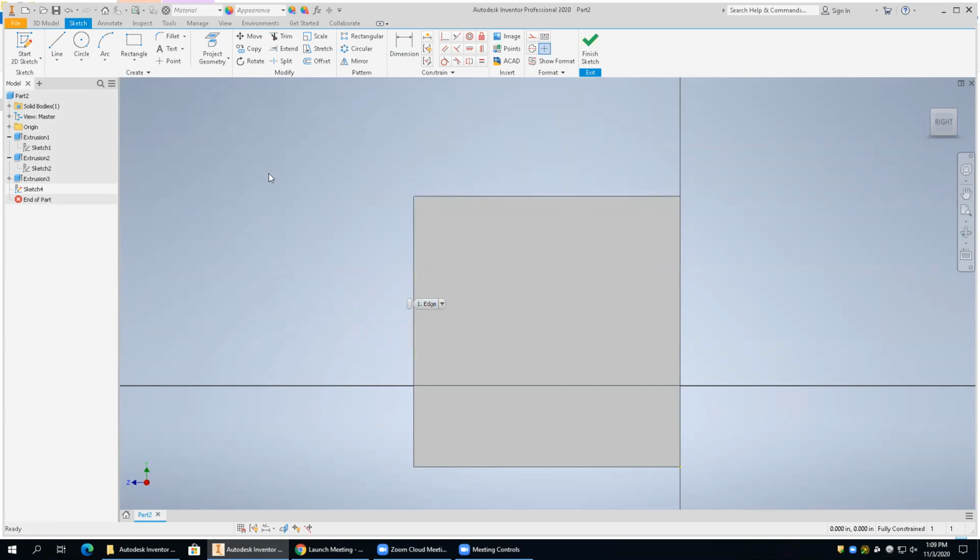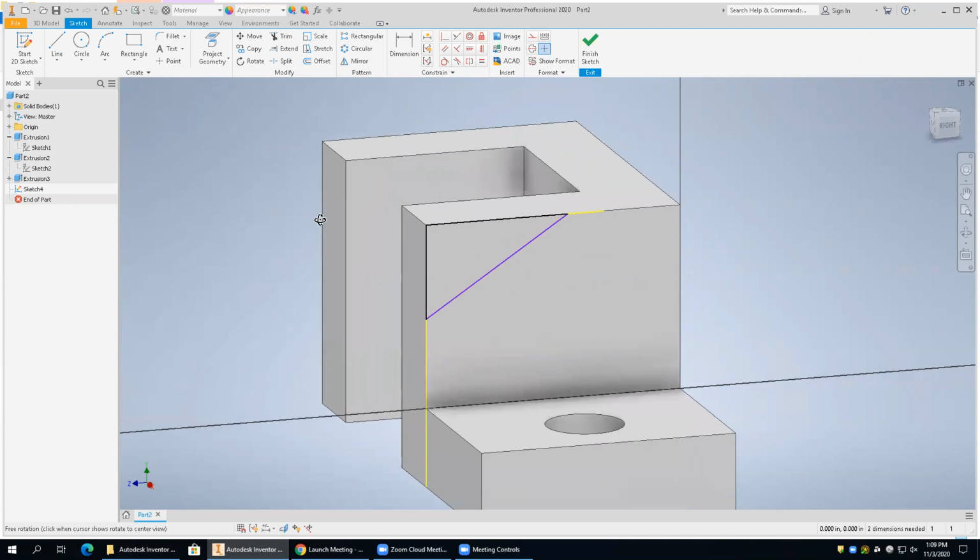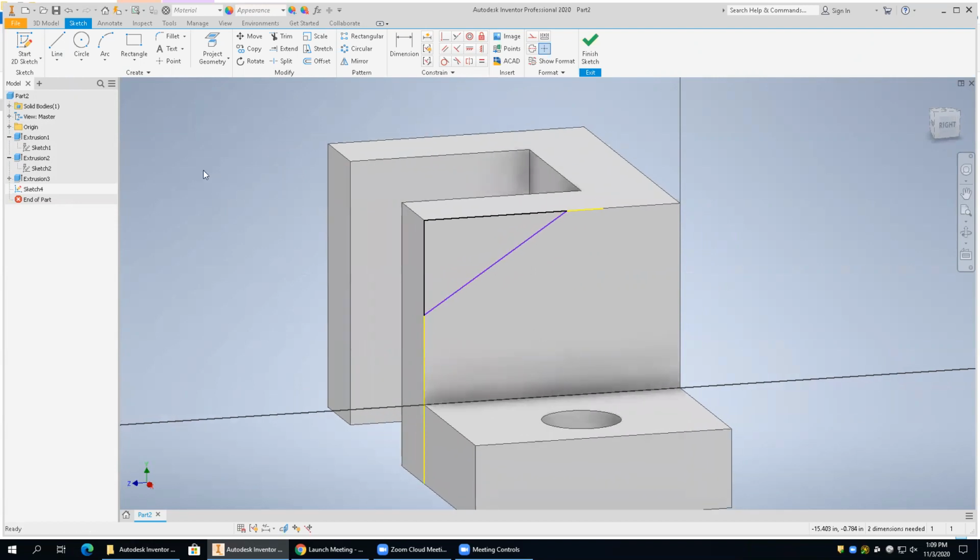Okay? So I'm going to do a line, snap it to that corner, draw it down that line. You'll see a little symbol pop up that lets you know you're on the line. Okay? Then come back up and touch that little O-snap, bring it down to that face, and then do it again from there up to there. So you should have 3 lines when you're done. If you're not sure, you can do a shift right click so you can kind of see, like I did right there, how that looks. So I have 3 lines. And they have to be closed or they won't work right. Well, we'll see when we extrude. Okay? We'll see when we extrude.